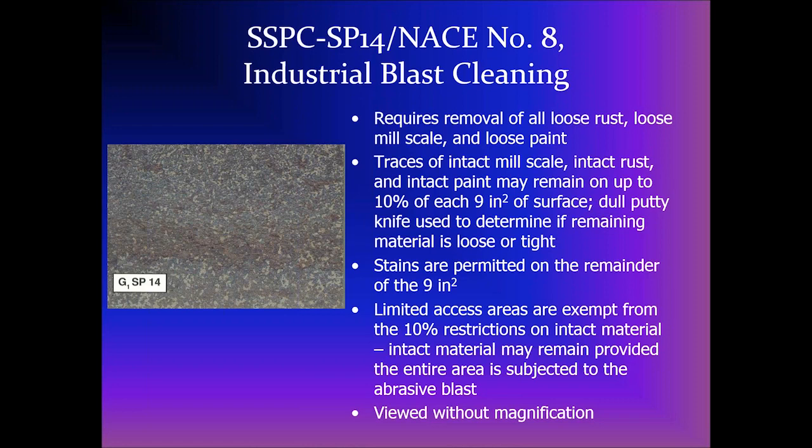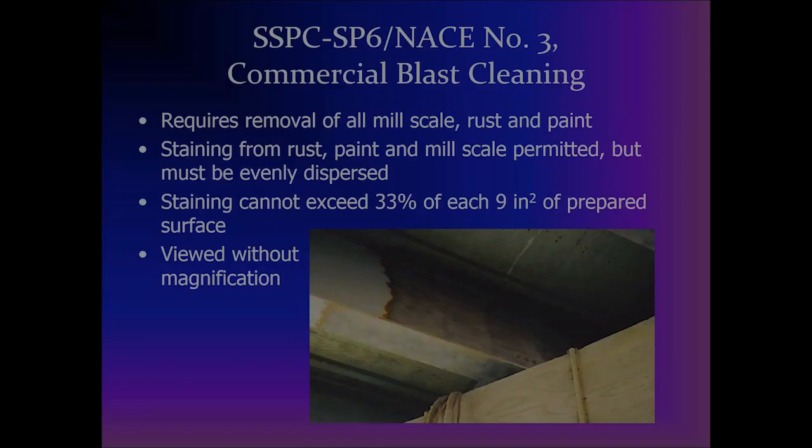It also allows more material to remain in difficult configurations, such as back-to-back angles. If, in fact, you would subject the entire area to the abrasive blast, and at the end of that time, the material remains more than 10% of the area, it's allowed, provided it's tight. And again, this surface is viewed without magnification.